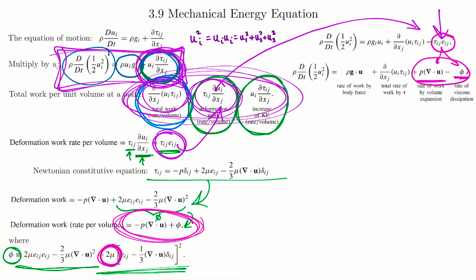Okay, so as I mentioned, that's a term that comes up a lot, right? So now you know in a lot of detail exactly what that viscous dissipation is, right? And it's proportional to the square of our velocity gradients. We can see from looking down here in our bottom left there, right? Square of the velocity gradients. And therefore it's more important in regions of high shear. And this heat that we end up getting from this viscous dissipation, where it's converting our kinetic energy into this internal energy, that's going to show up as heat, right? So that could be like a hot lubricant in a bearing, or we might see that as the burning of the surface of a spacecraft on re-entry. So it'll be things like that where this viscous dissipation would show up as heat.